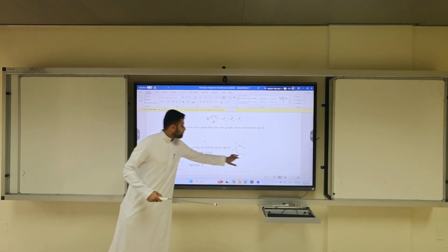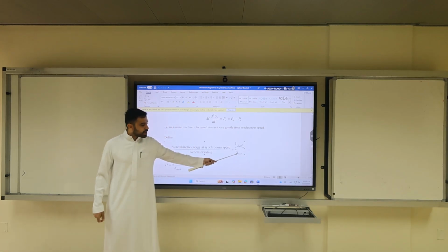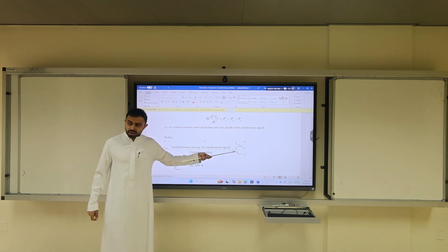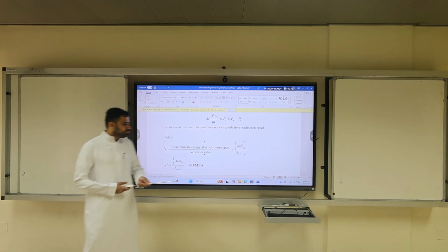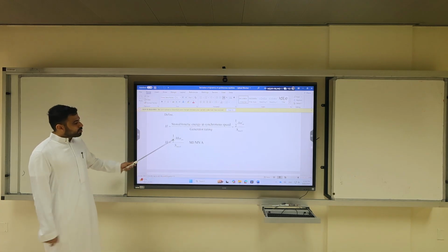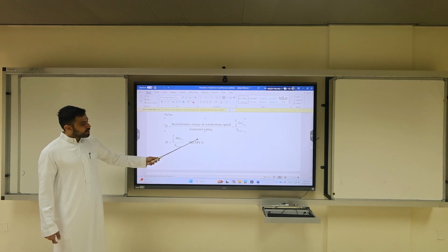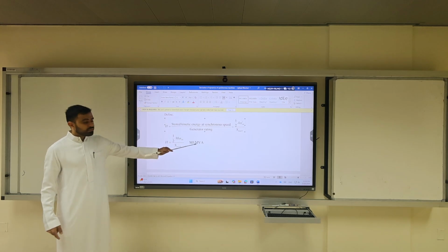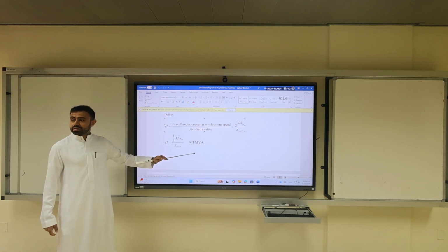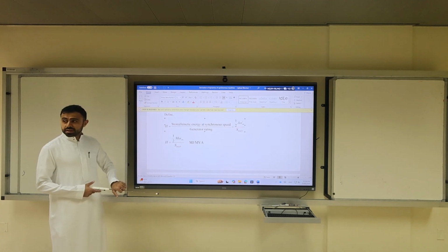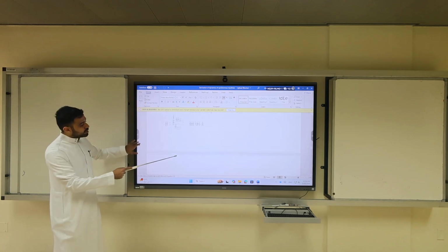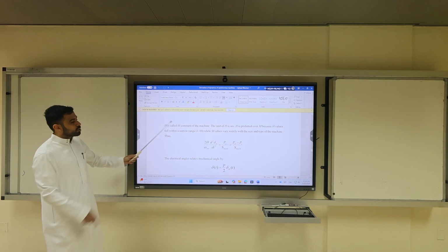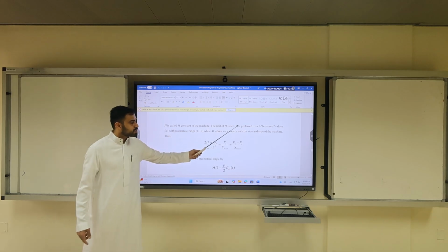Then what do you have? Divided by the rating, the apparent power. So you're dividing kinetic energy over MVA. Okay? Now, this is megajoule over MVA. Joule is energy, MVA is power. Energy over power is what? Time. Get it? Isn't it? Yes. So then you go next to H as the inertia constant. The unit of H is seconds because it's time.